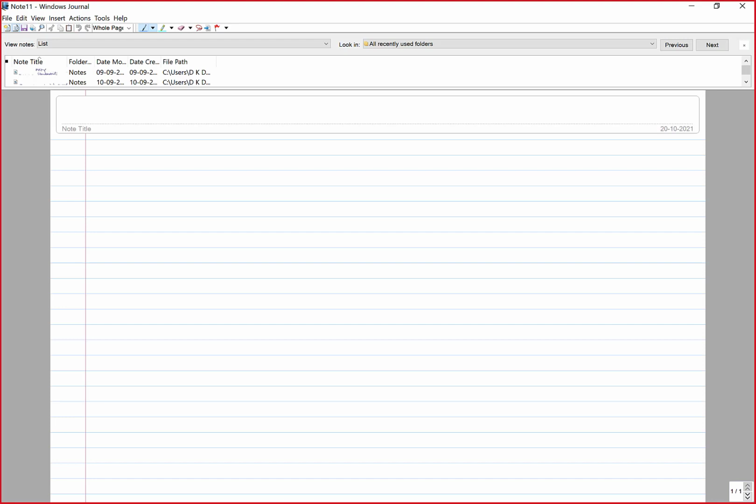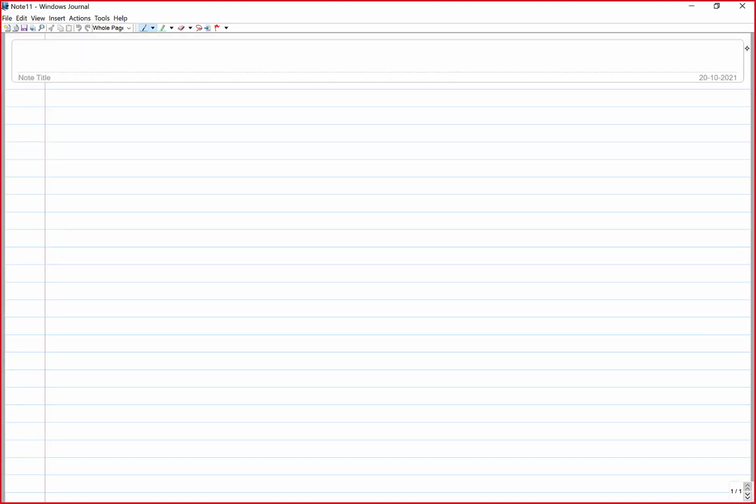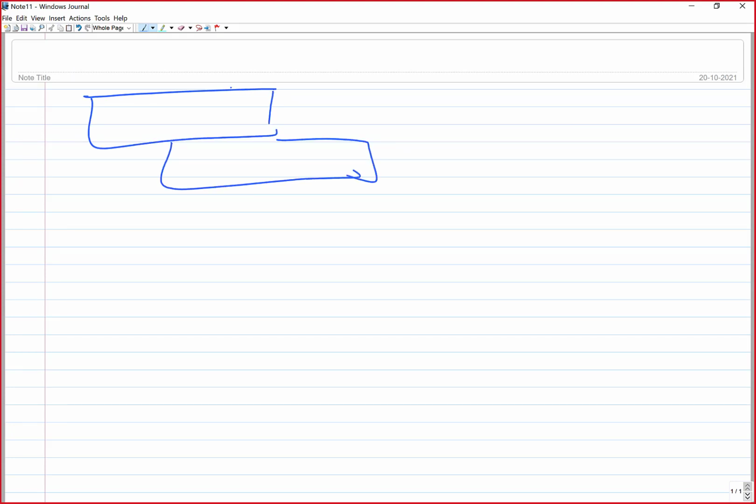Then we have some other interesting and very good features. The moment you make a spot weld, you get depressions and impressions at the surface of the base metal. This damages the appearance; appearance is compromised when spot welds are made. When you make adhesive joints, there is no compromise with the appearance, no decolorization, which may also be caused at the surface due to high temperature rise, and no impressions, depressions or spots at the surfaces. So all those issues are resolved. Appearance-wise, the adhesive joint results in a quite good surface. That's why it is extensively used in a number of car body parts for joining purposes.